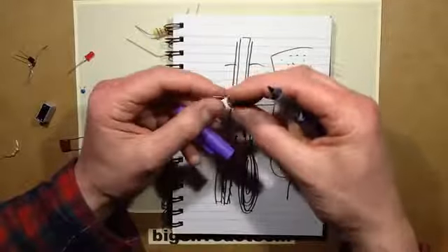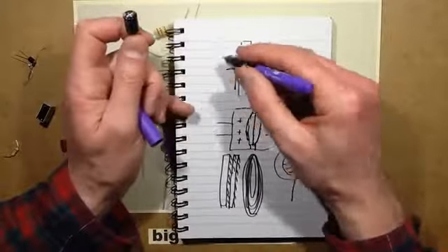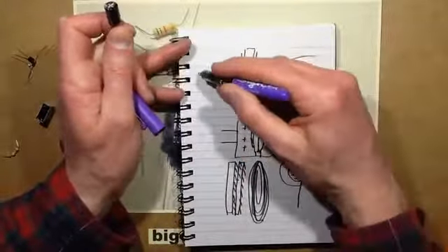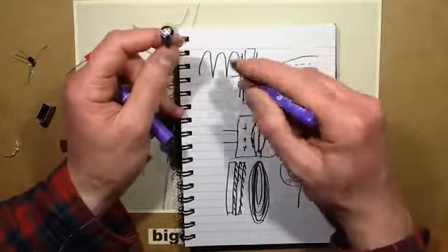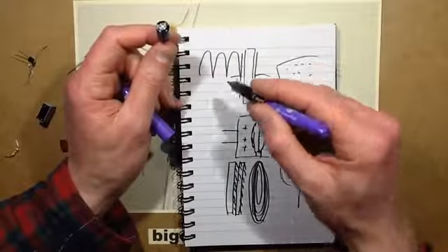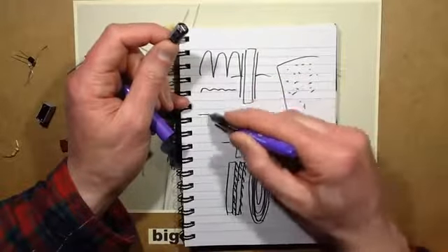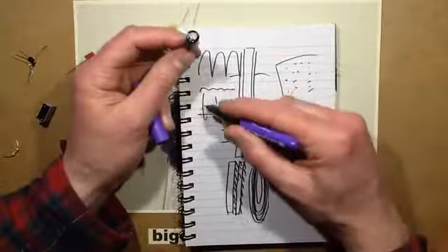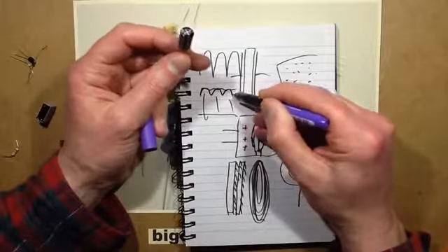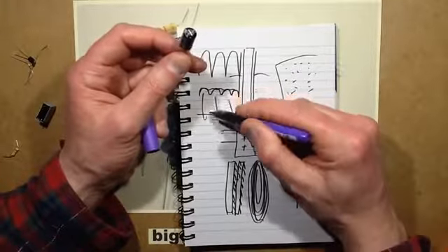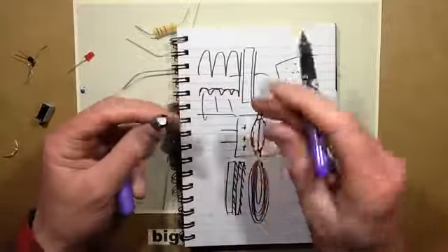When you get the large values like this, they're usually used to smooth ripples. So say for instance the output from the mains was rectified, and you had a big peaky full wave rectified AC waveform, which is like the two sides of a sine wave. By putting this across that, it reduces it to a very slight ripple and a nice smooth DC voltage. And as that capacitor dries out over time, that ripple will get bigger, and it ultimately starts causing problems when it dips down so low that the electronics can't sustain normal operation. And that's when you have to change capacitors.